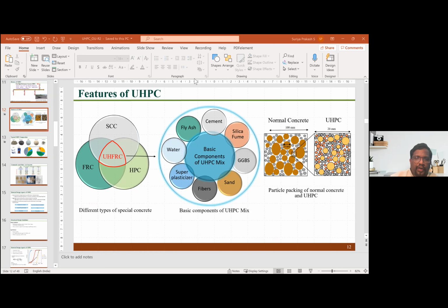That's why we have taken 100 mm, so that your aggregate sizes are properly considered. I cannot go for larger size specimens, then you will have dispersion effects. So that is one of the limitations. We cannot go for a larger specimen size, because then your one-dimensional wave propagation assumption itself will not be correct.